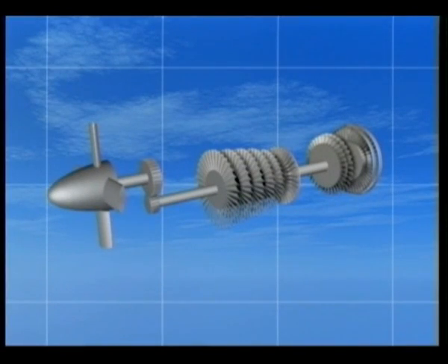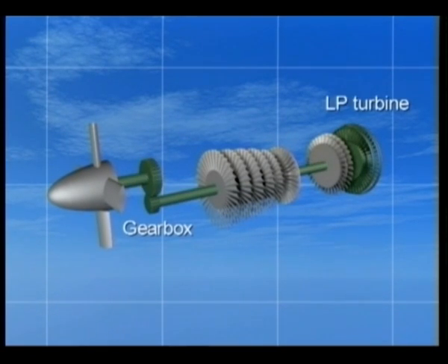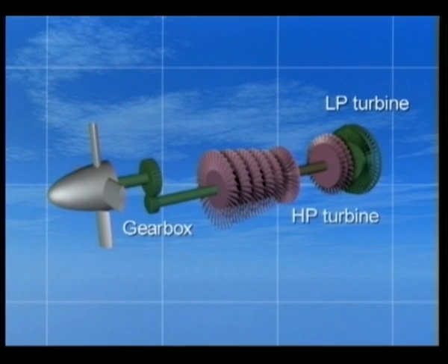The basic principle behind the free turbine is the same as that already mentioned. There are usually two shafts, one driving the low-pressure compressor or gearbox, and the other driving the high-pressure compressor. The rear turbine, normally called the low-pressure turbine, drives the low-pressure compressor at the front of the engine or the gearbox. The front turbine, normally called the high-pressure turbine, drives the high-pressure compressor.